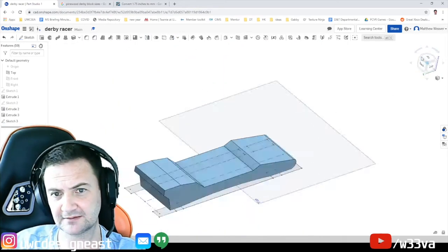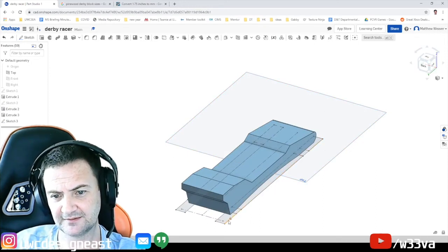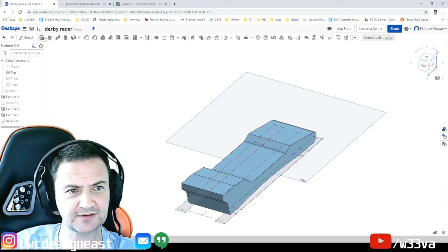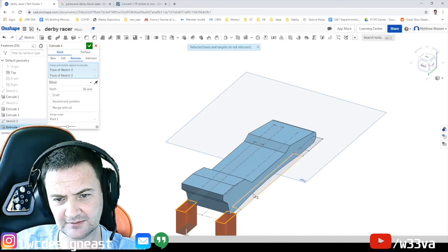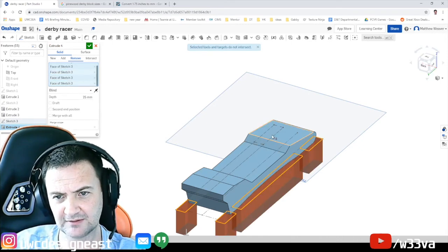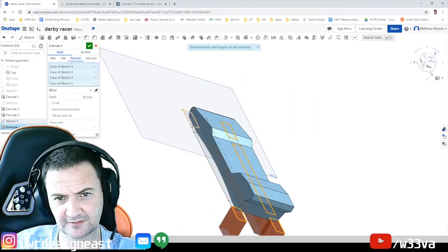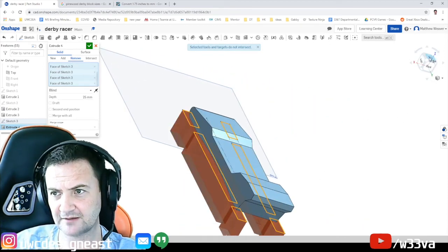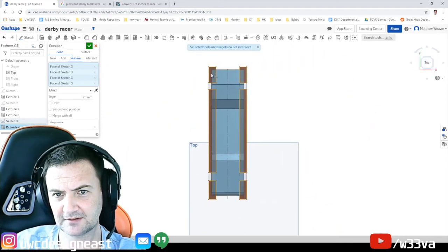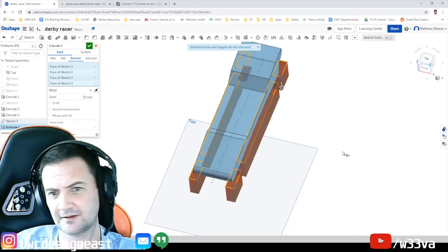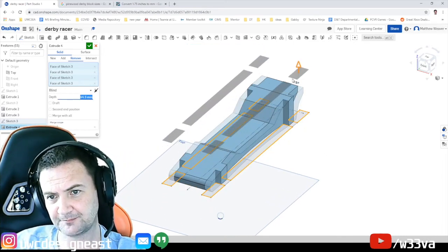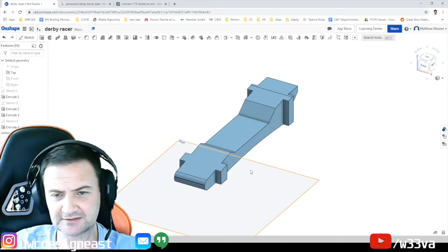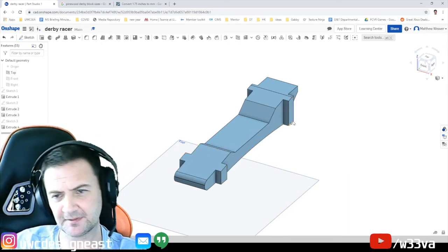Now if we go back to this area, you can see these are the lines that I'm going to now extrude. So let's extrude and subtract. So we're going to remove that one and that one, but we're keeping that one, that one. Let's turn that around, that one and that one, and we're going to keep the others. Okay, so like I said, remove, keep. They're the parts of the car that we're going to attach the wheels to, and just drag those up, and then you can press enter. So now we've got a much smaller amount rubbing against that wheel.